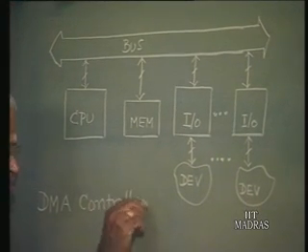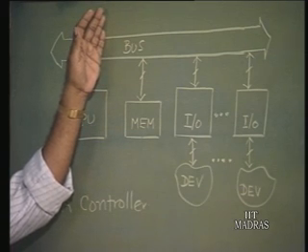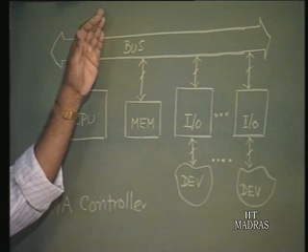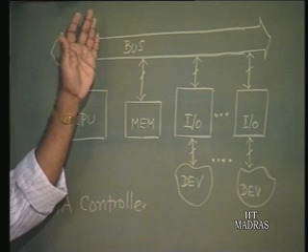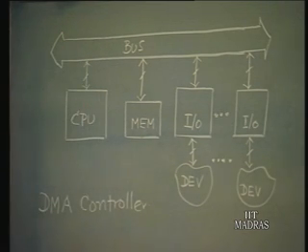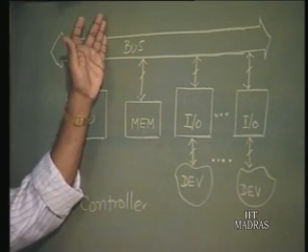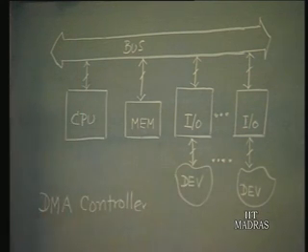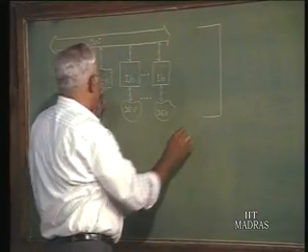Okay. So, we had seen that in the case of programmed I/O, the processor is very much involved. In the case of interrupt, the processor is asked to be involved, and in the case of DMA, the processor will be informed, okay, a very fast device is coming, there is going to be a very fast data transfer. So, you just cannot handle it, keep away, this is the kind of thing, right. So, the device when it is ready will inform the CPU, obviously over the bus lines.